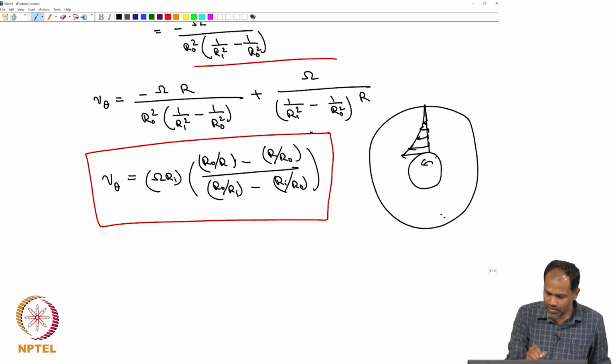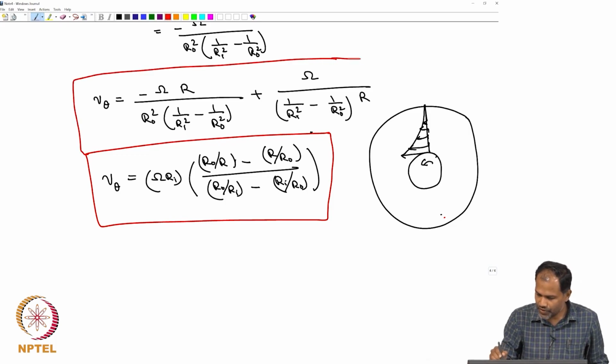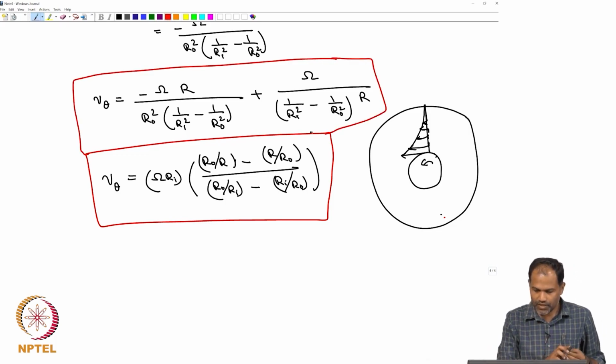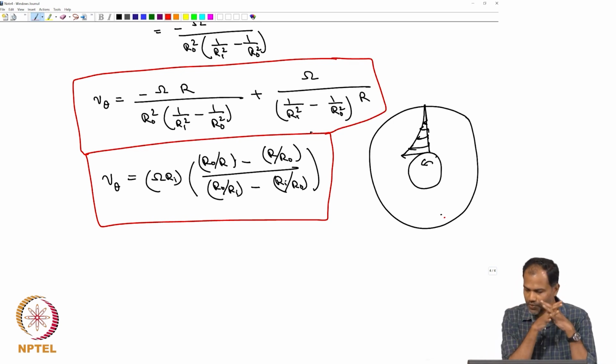We just box that. That's the expression. You don't need to remember anything. It's just the information that you get when you solve the cylindrical problem. It also tells you how you should deal with equations in cylindrical coordinate system, how some of the non-trivial terms contribute, and the pressure and centrifugal force balance is the other thing that nicely came out of this analysis.